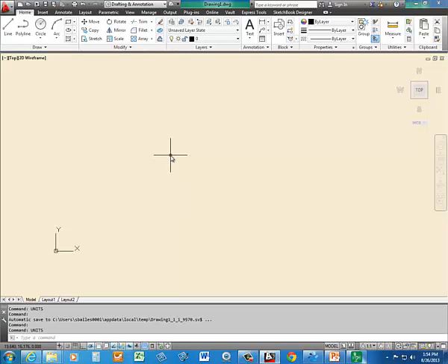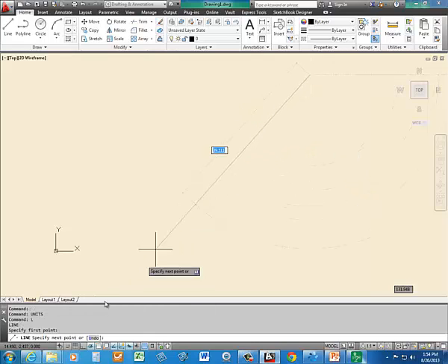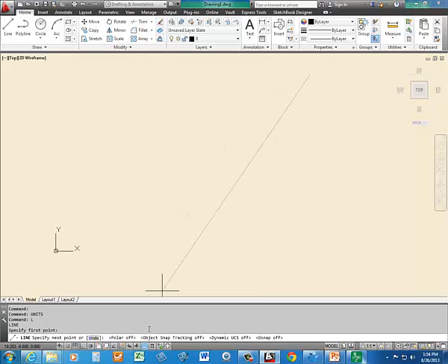When you type in the various lengths, you're going to use no kind of snaps. You can turn off everything down here, and all you're doing is entering the old-fashioned relative polar. So I'll try to type in the first one. You can see it's displaying down here in the command line.